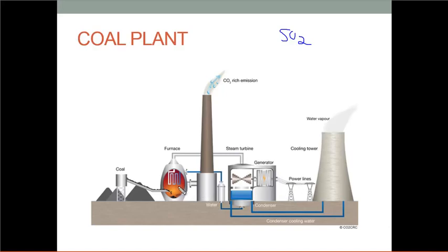So the emissions of the power plant are an important thing. And we're interested in SO2 emissions, which is from sulfur in the fuel, right? And SO2 makes acid rain. And I mentioned in the very beginning of this lecture that I worked for the power company and did emissions monitoring, the CEMS, the continuous emissions monitoring systems.